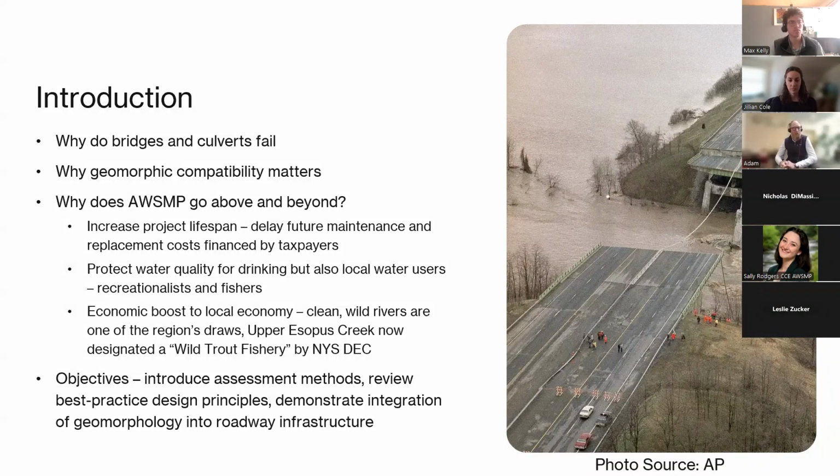So why consider geomorphic compatibility and why does that matter? Really the main focus and takeaway from this presentation is that by including geomorphic compatibility in road stream crossing design, you can really help reach the structural lifespan of a crossing so that you don't see premature failure. And it also helps reduce costs associated with that crossing failing prematurely or repeat maintenance needs.